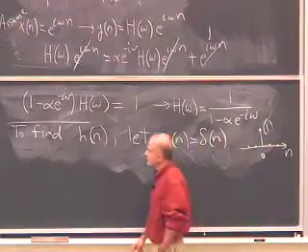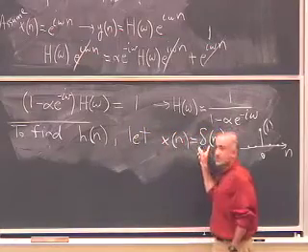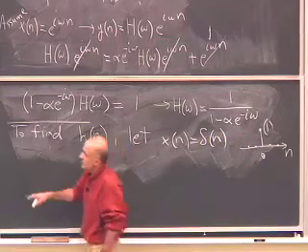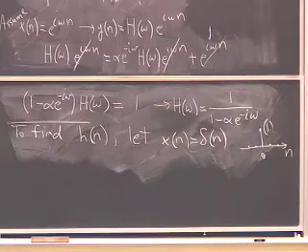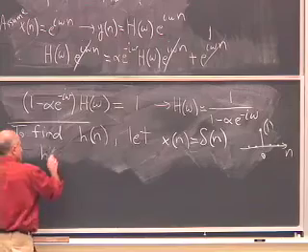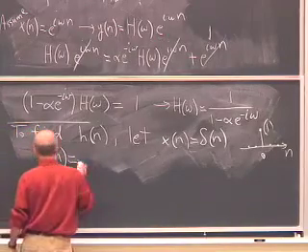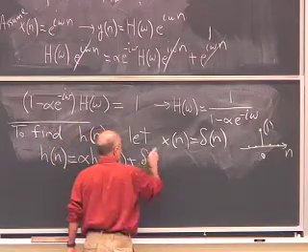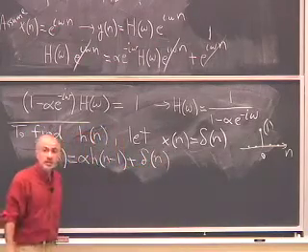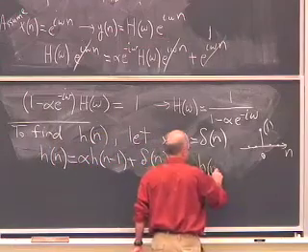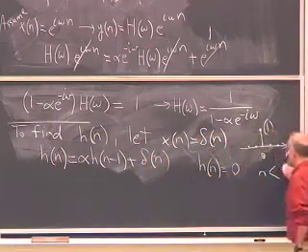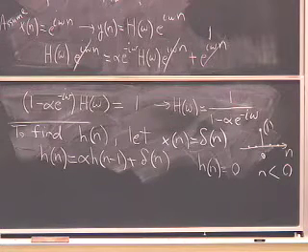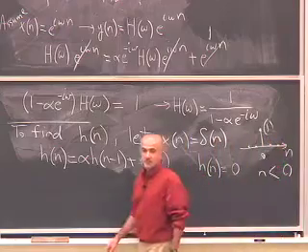Okay? When the input is the impulse, the output we call the impulse response. And so instead of calling it y, I call it h. So the same recursion holds, except now wherever I see a y, I replace it with an h. h of n equals alpha h of n minus 1 plus delta of n. Okay? And h of n is 0 for n less than 0, because I've told you the system output is 0 for negative time. Now let's start going from n equals 0.